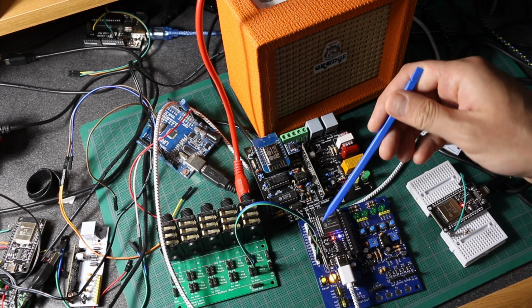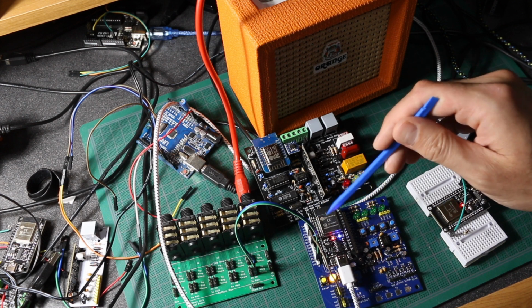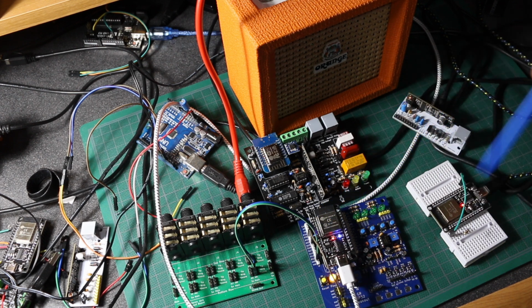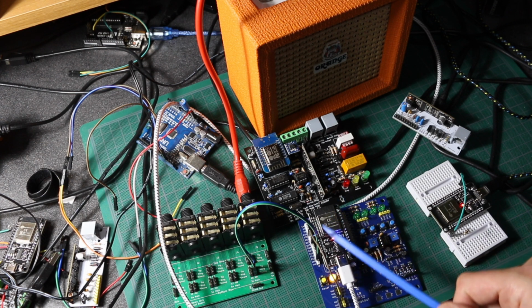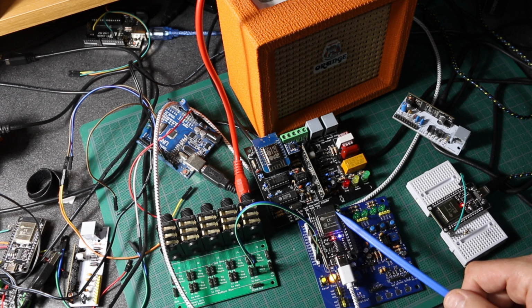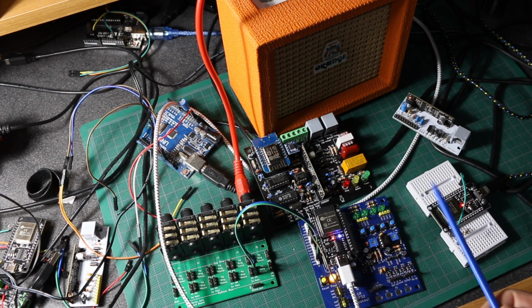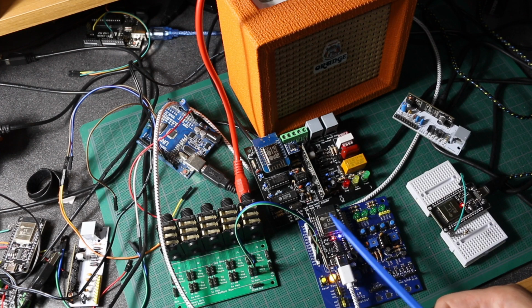So in my test setup, this module on the dev board is set up to be the server, and this other one is set up to be the sender. So right now, when I power up, this one is going to try to join my router. Then it's got its internal web server, and it will try to auto pair with this other module over ESP-NOW. And when everything's good, they'll both send data packets back and forth, and this one will update data on the